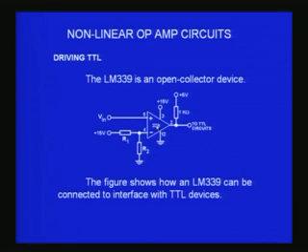For example, in this picture, you have V in, and an R1 R2 divider to get a V reference here, and at the output I have connected plus 5 volts through a 1K resistor. So this comparator is compatible with digital circuits, because now the output can never be more than 5 volts or less than 0 volts.